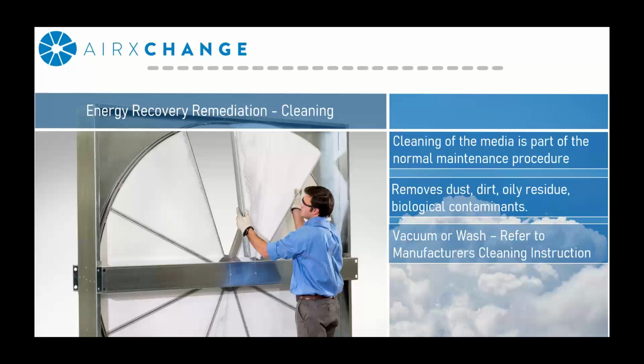The benefit of the soapy solution is it allows you to get a nice deep clean of the heat exchanger surface area. It also provides a hygienic approach, as you wash the segments outside the HVAC unit, and you don't run the risk of introducing any potential contaminant into the airstream.